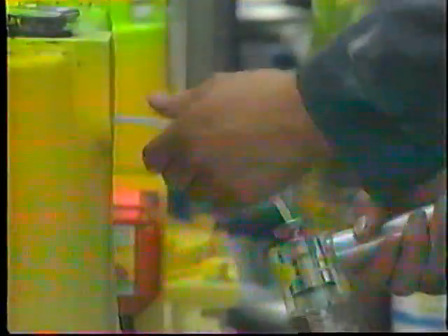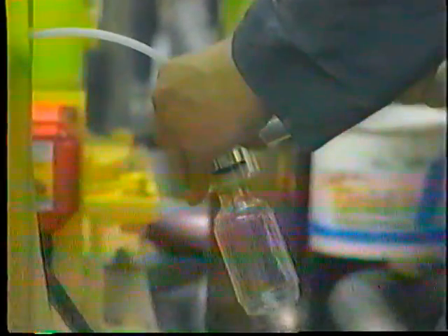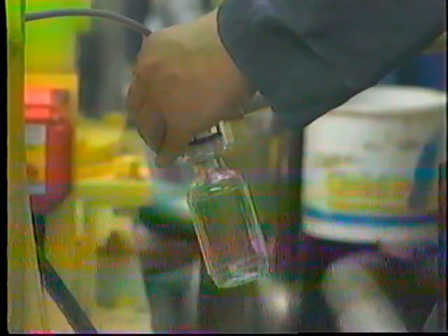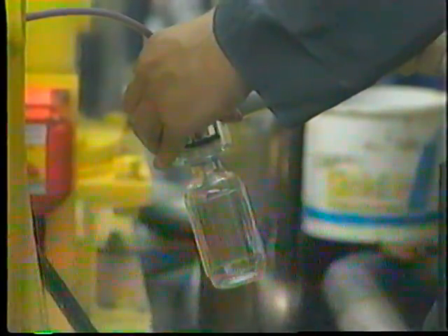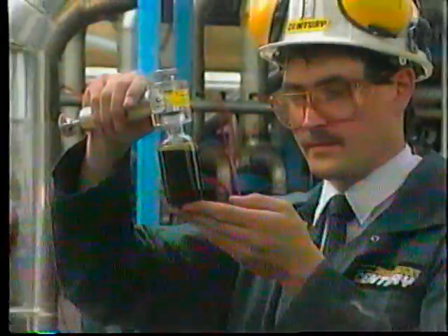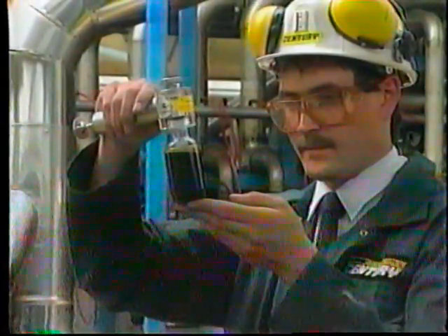If your facility has a predictive maintenance program, routine oil samples will be taken and analyzed. These periodic samples will allow wear and contamination to be spotted much earlier and much more accurately. In this lesson, we have seen the common types of lubricants, examined their characteristics, and seen how they are used in modern industry. By applying the principles of proper lubrication in your workplace, you will almost certainly extend the life of mechanical equipment and reduce the occurrence of lubricant-related failures.